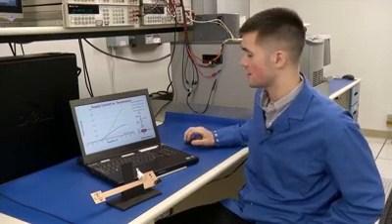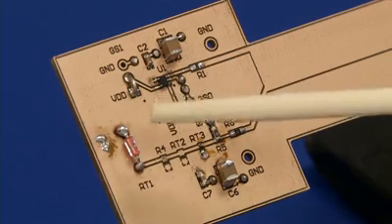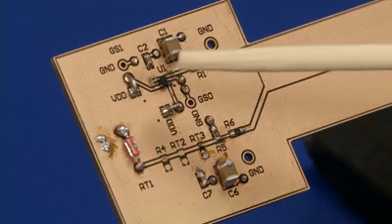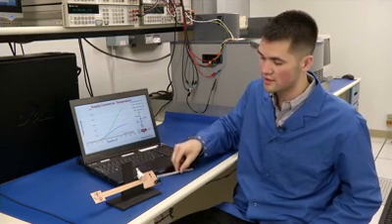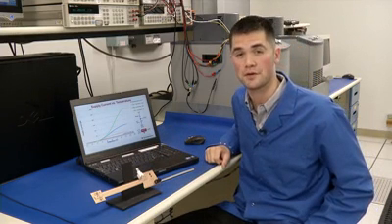So how do we come up with this data? I designed a test board here that compares NTC thermistor networks with TI's LMT87 analog temp sensor. We were able to record the data by using the oil bath setup behind me.